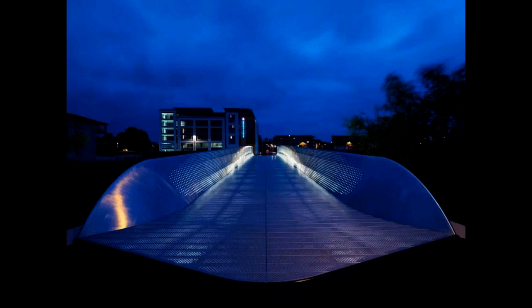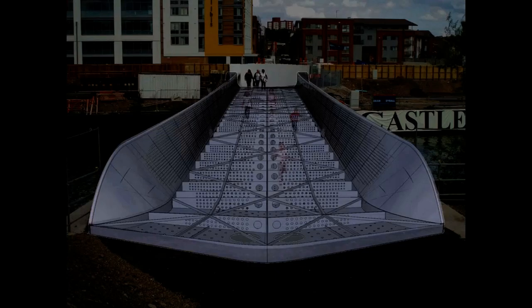Now this goes back to what we were looking at earlier on, perforating materials in order to lighten them. So what the engineers did was they looked at the overall structure. Okay, it's a folded structure, so the beam itself is, you know, that depth, isn't it? It's a U section, but that's the depth. The span to depth ratio is all about this, which looks like the handrail. It's folded to give it stiffness and strength. There's a certain amount of reinforcing in the lower part, and here are little miniature bridges. So there's a truss here, if you like, a perforated truss here, a series of little perforated beams connecting through to them. So that's the overall hierarchy of structure.